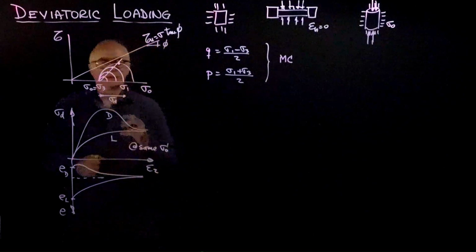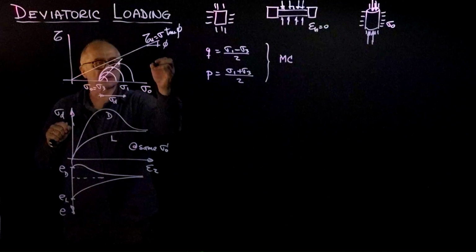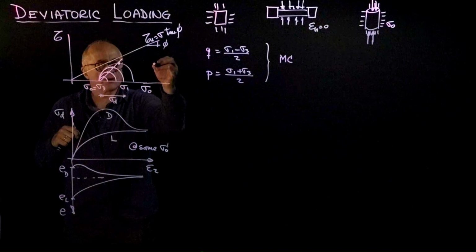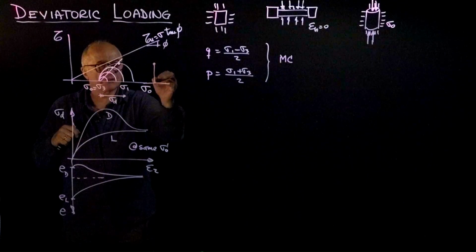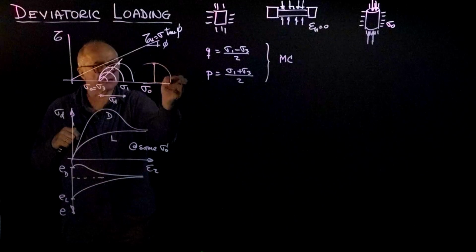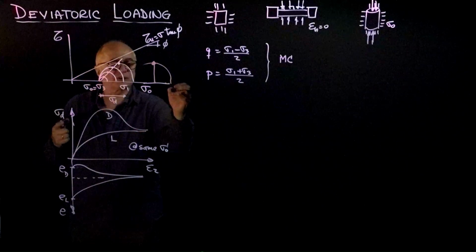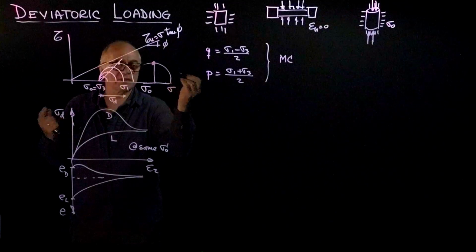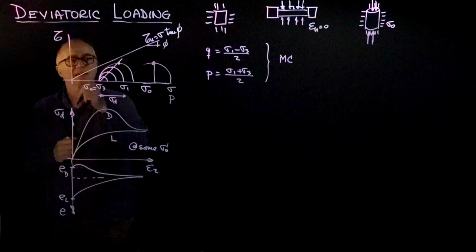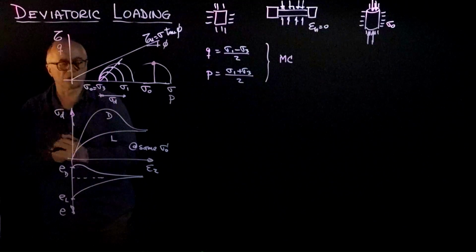Once again, if you ever get lost when we are dealing with q and p, and I just show you a point, always realize that you can lower that point, find the center of a circle, and draw the circle that point represents. Therefore, we can always talk about this axis as both sigma if you are drawing Mohr circles, or p if you are drawing the apex, and tau if you are drawing Mohr circles, or q if you are drawing the apex.